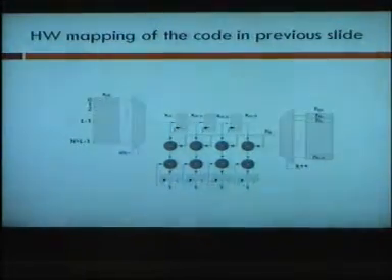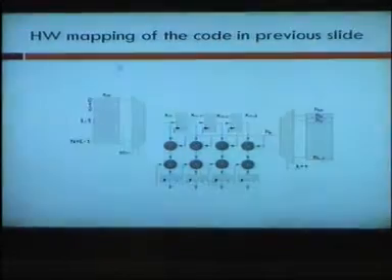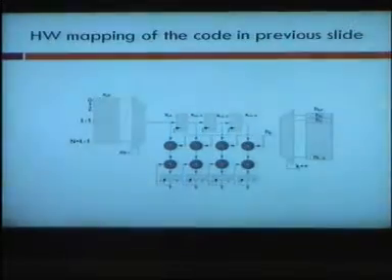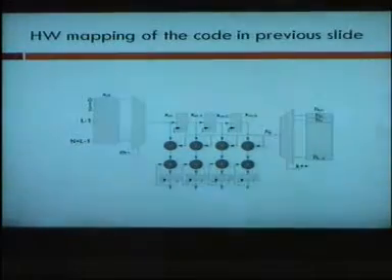But here, first of all, you are not wasting any time maintaining loops or calling functions. Data just comes into this buffer directly and it gets updated. The whole thing gets updated: new value comes in, old value goes out. So you are not really running any piece of software. It's just the hardware taking a value and throwing the old value away from the register at the bottom, so it's automatically working in lockstep.